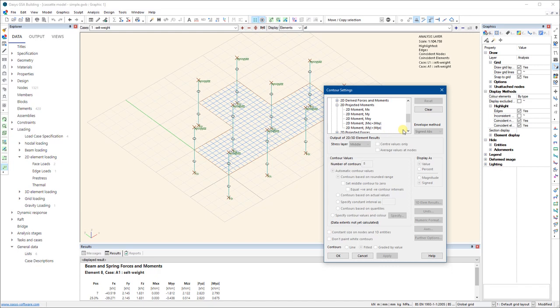So hopefully you're familiar with the Wood-Armer type rules or something similar, where you take the bending moments in an element, combine them to get the design moment. And this essentially is a quick, simple and conservative way to actually get that combination and display it. So again, that's quite helpful. But you can go through these in your own time. Again, it's all fairly self-explanatory.